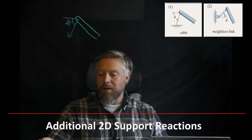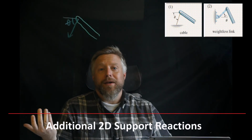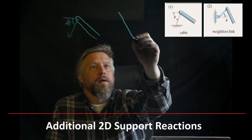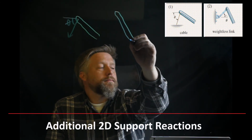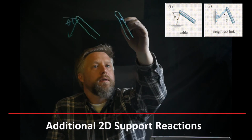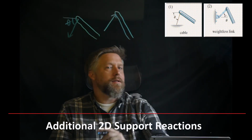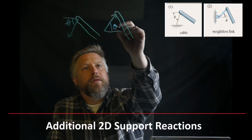So it's very similar to a rope, but it's a rope that can push. So a weightless link, we're going to do a very similar thing. We're going to draw the body it's acting on, and we're going to draw a force acting in the same direction as that weightless link. Make sure to mark our theta on there.